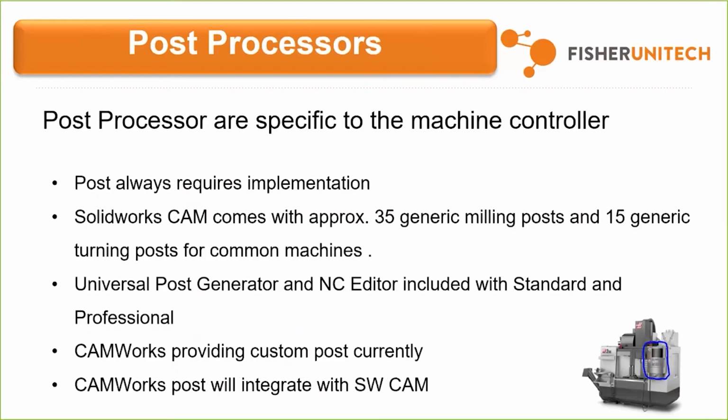Okay, so this is a pretty important one, especially for beginners in CAM. The post-processor, we actually get a lot of questions about post-processors in tech support. So basically you have SOLIDWORKS CAM, right? And SOLIDWORKS CAM is creating this G-code, and it's got to talk to the machine. But in order to talk to the machine, we need something to translate it in order to talk to your machines. And that's where the post-processor actually comes in. So you always have to have a post or post-processor.